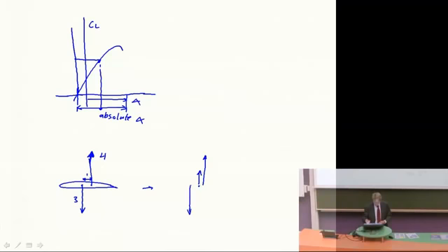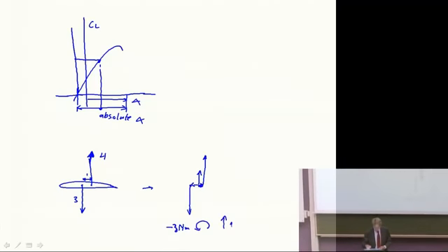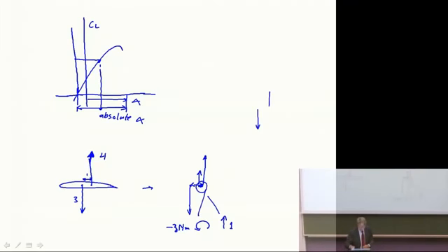And we have a force up of 1 Newton, all applying at the same position here. So we decompose the two forces into a moment and a force. Well, if you translate a moment which has equal force up and down, which is basically a couple of forces, then if you move to another reference point, you can see that that shift, that translation, is added to your moment both on the plus and on the minus side. And therefore it doesn't matter.